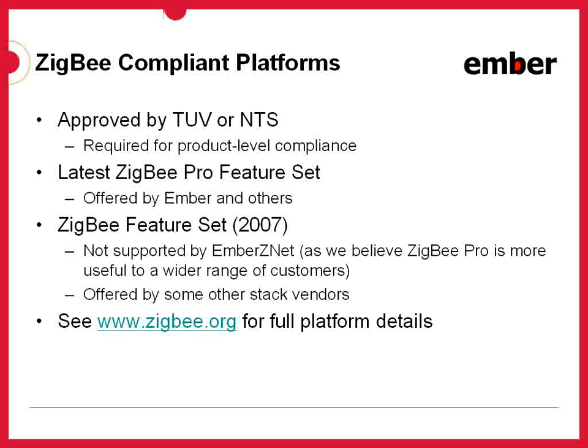In order to ensure that the stack, the ZigBee networking layer, as well as the MAC and the PHY, has been implemented in a standard way that complies with ZigBee protocol and interoperates well with other stack designs, ZigBee platforms must go through compliance testing at a ZigBee-approved test facility. These test houses are TÜV and NTS, both of which have previous testing experience with other networking designs and provide global testing facilities for customers worldwide. Application designers wishing to build a ZigBee-compliant product, advertised as such with a ZigBee logo, must have their design based on a ZigBee-compliant stack platform.